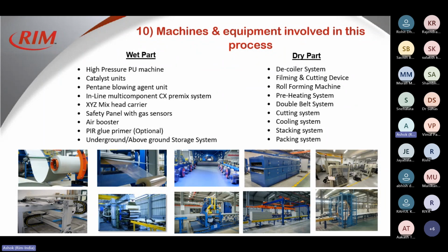agent, then an inline multi-component pre-mixing system, an XYZ head mixing head carrier or crossbar system, a safety panel with the gas sensor for pentane safety, then the air booster for air nucleation, and PIR glue primer. Those companies are producing PIR, so PIR glue primer is a must. And some auxiliary storage tanks, including the underground storage tank for pentane.